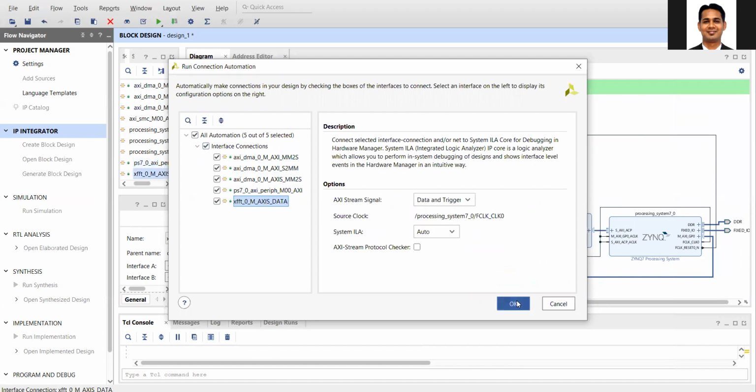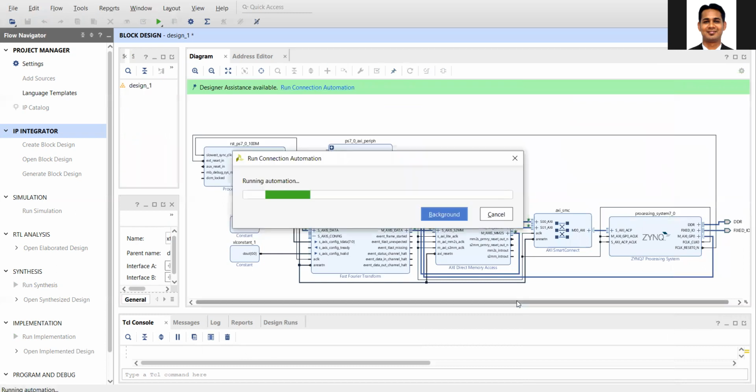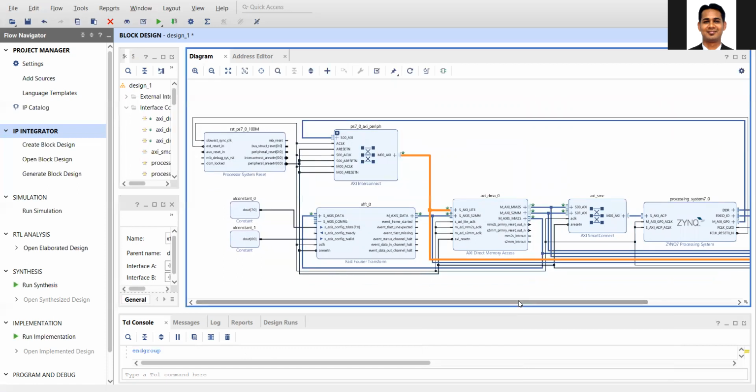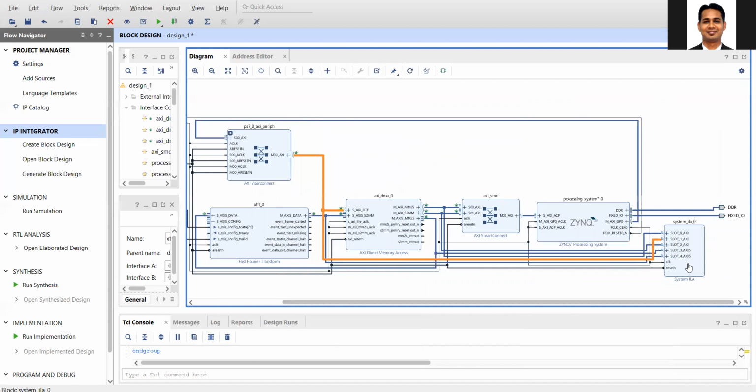So this logic analyzer is the integrated logic analyzer. When we are running our code on the board, it captures the data when the corresponding trigger condition is set, and passes it to the debugger, so that our tool can display the data. So when our code is running on the board, the on-chip data is being captured and displayed in the Vivado tool. That's why we will see what is actually happening inside our chip via this integrated logic analyzer. Okay, so this is the logic analyzer.